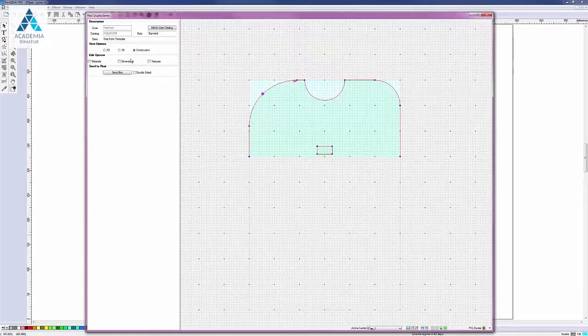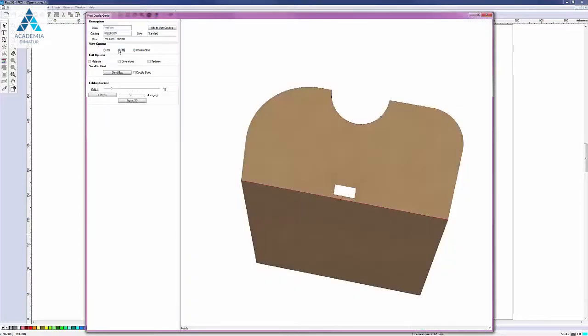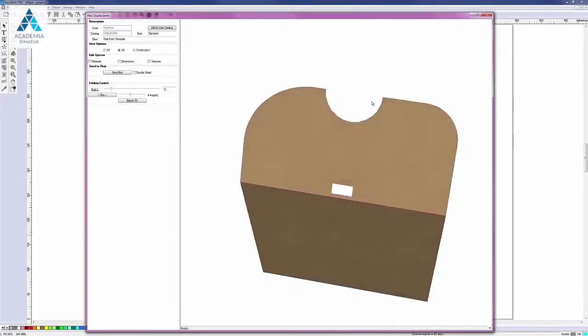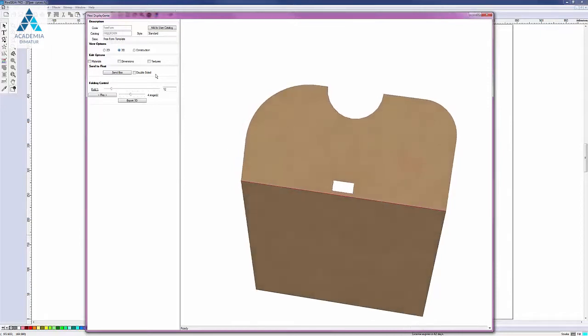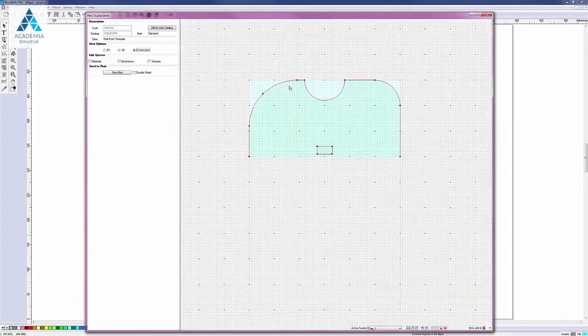Okay, so I'll just look at that in 3D, and nice and smooth. So this is a requirement for CNC milling programs. They only work on circular arcs, not on arbitrary arcs. So we've fitted the arbitrary arc using two circular ones.